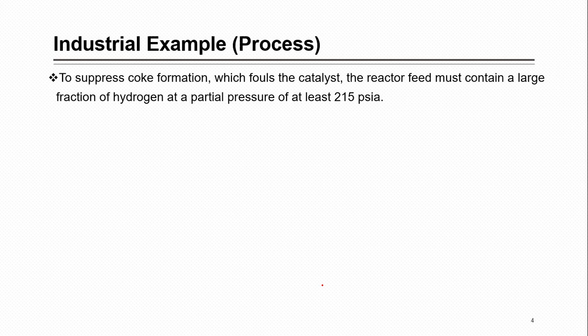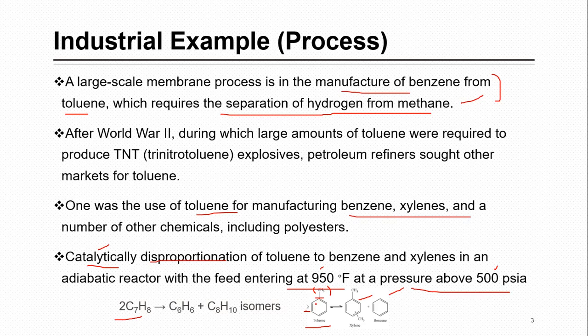And when coke formation takes place, what is the disadvantage? When your molecule is broken down into carbon and hydrogen, it is a loss of material, that is feed, and some product can also be converted, like paraxylene, benzene, as well as toluene. All these three are exposed to this cracking reaction, so they are lost, and your product is lost.